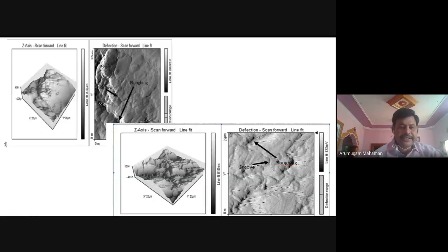This is the atomic force microscopy image we created. Here you can see that we generated nano surface finish. So nano finish, you can see. Here we generated a 939 nanometer surface. You look at this. If you are using some other processing condition, we got a 329 nanometer surface. So that much lower nano surface finishes we developed.